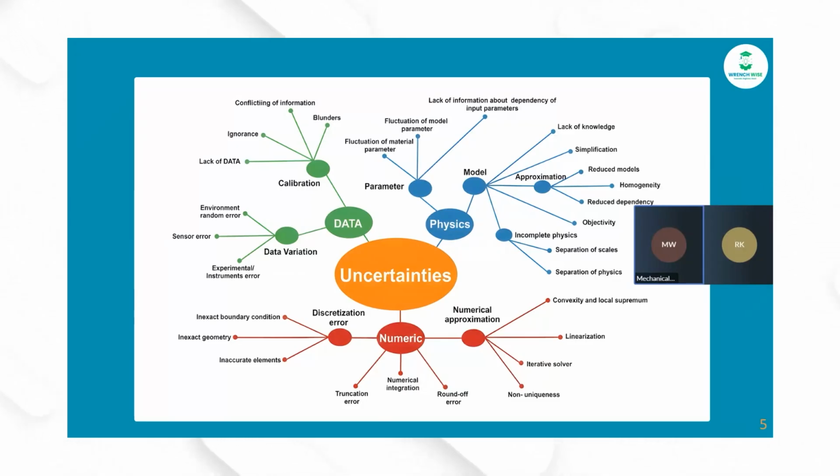If you have highly curved geometries like a turbine blade, this may end up with flat cell faces. This is called faceting. Or you may also introduce inaccurate elements using a mesh that is too coarse or highly skewed. These will fail to capture the gradients that we actually want for boundary layers or for shock waves, etc. Similarly, since computers cannot afford to store every single data point in very high precision, there's also the round-off error, the truncation error, and the iterative solving itself.